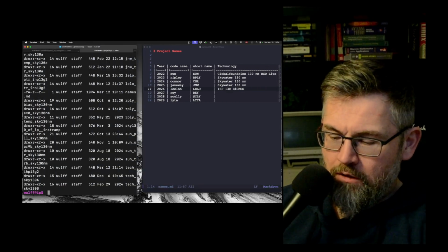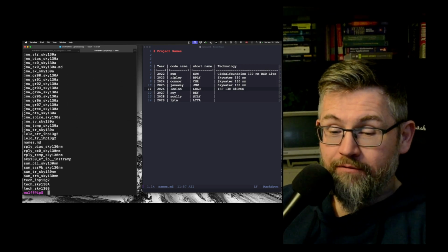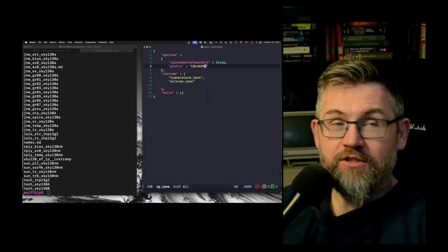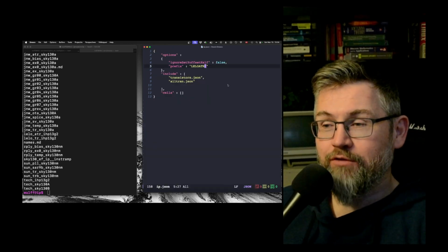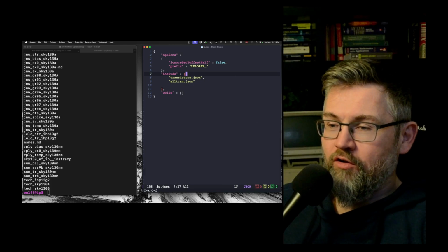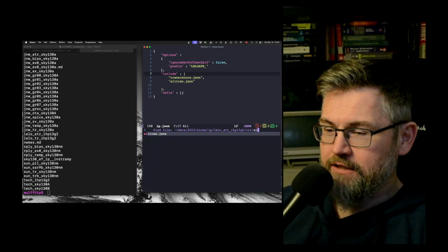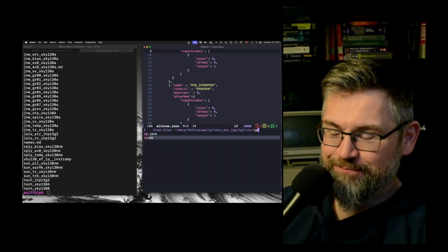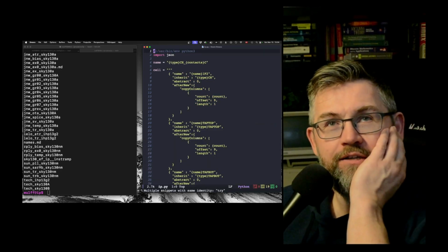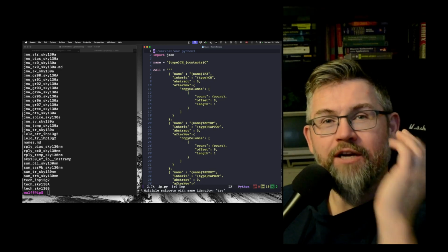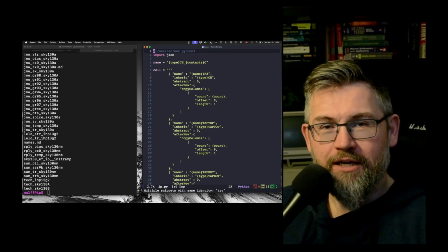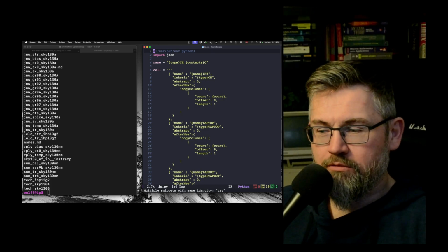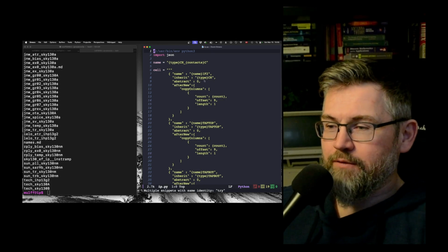Anyway. Oh, and the reason I do have different names for everything is I want every single schematic to have a unique name. And that's just because if you're going to have a big chip, you can't have two schematics called the same thing, or two cells called the same thing. Then you will run into trouble. So better make a strategy to have them unique.